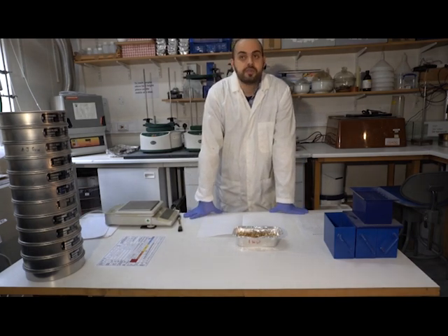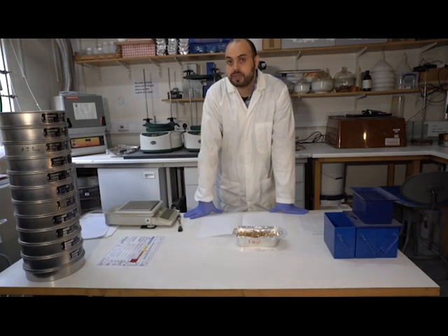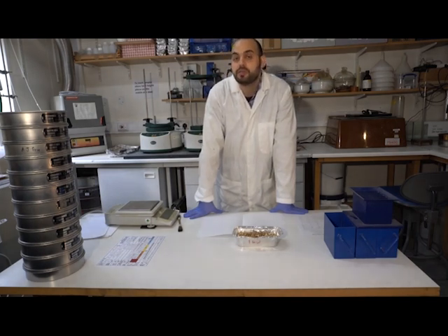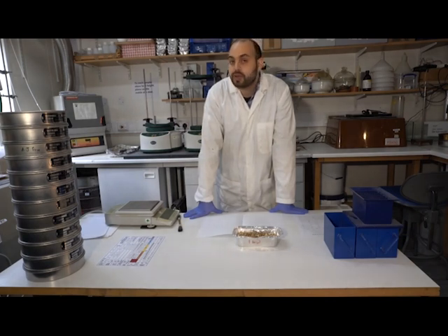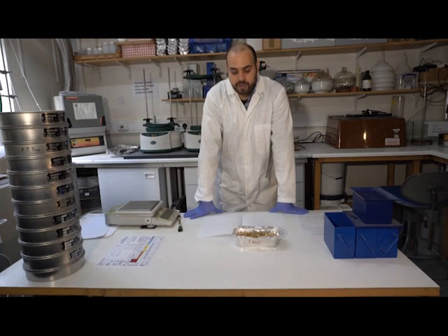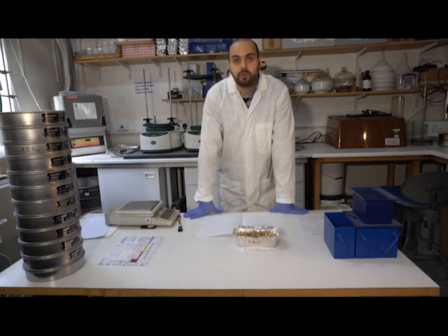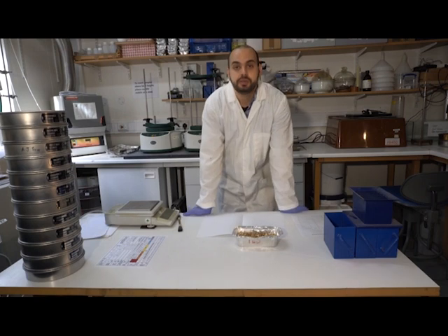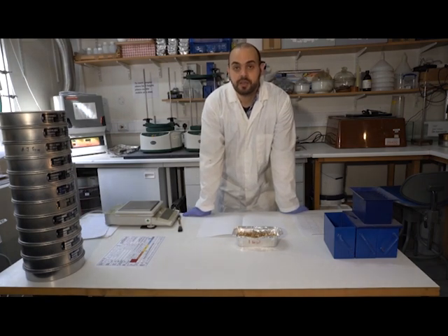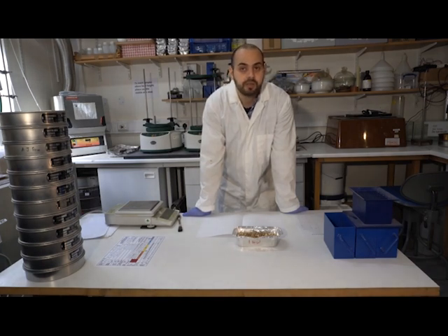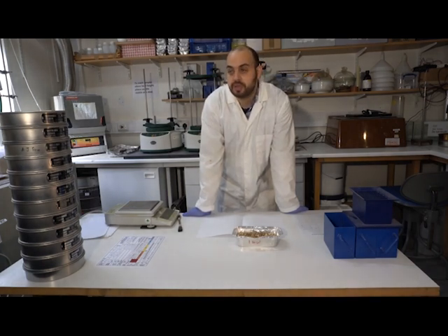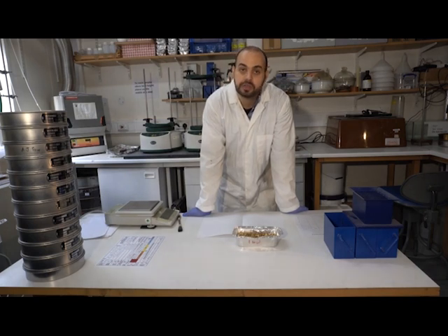Now, particle size distribution is really important because if we want to construct a building or a structure above soil or sediment, then the strength of that soil, its bearing capacity, is really a function of the sediment size and its sorting or packing. The same applies if we want to describe how water flows through an aquifer, for example, because again, the speed at which water could flow through this porous medium depends on how tightly packed these particles are, and that's really a function of their composition.